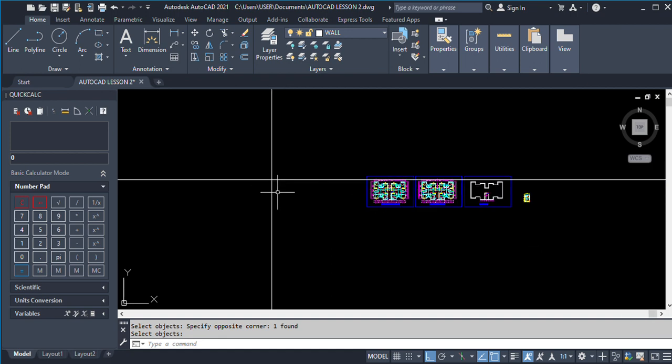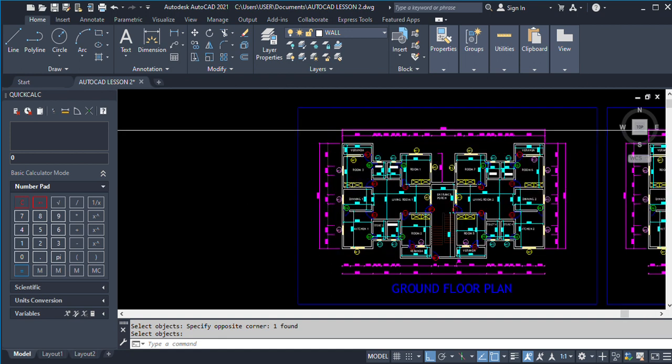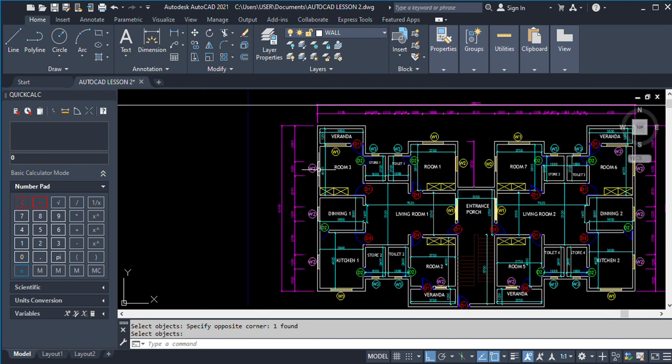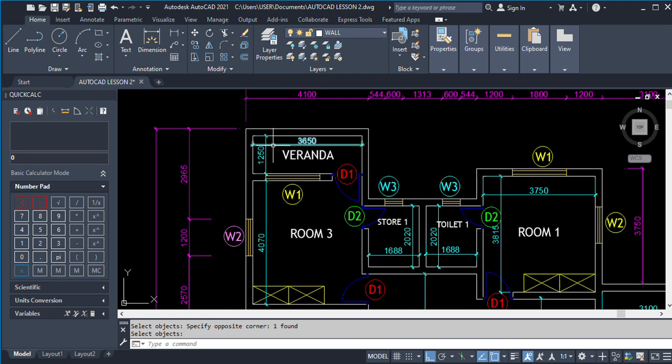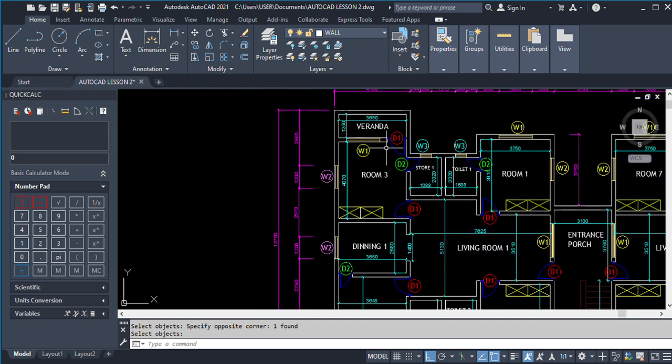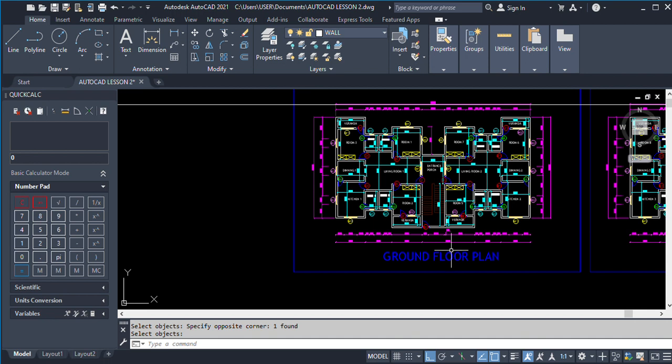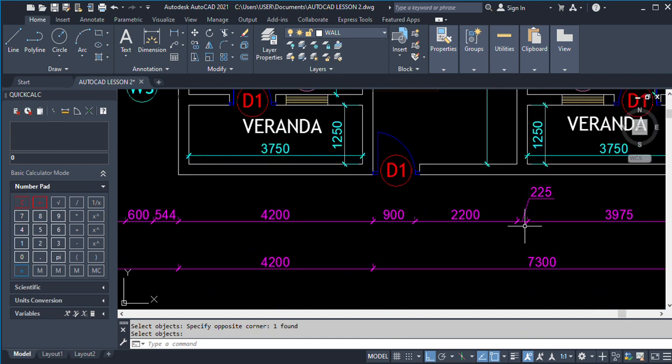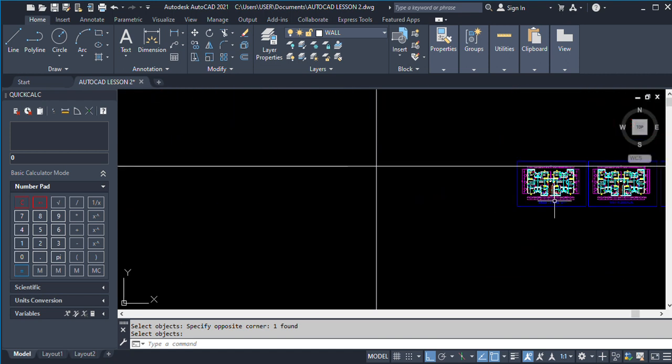So now let's start. I'm going to offset from left to right. First of all, I have here the next wall. The next wall is at the interval of 4,000. Okay, let me use the internal measurement, 3,650 mm. The wall thickness is labeled somewhere here. Wall thickness is 225, so we are going to adopt 225 throughout. So first of all, let's have that wall thickness offset.